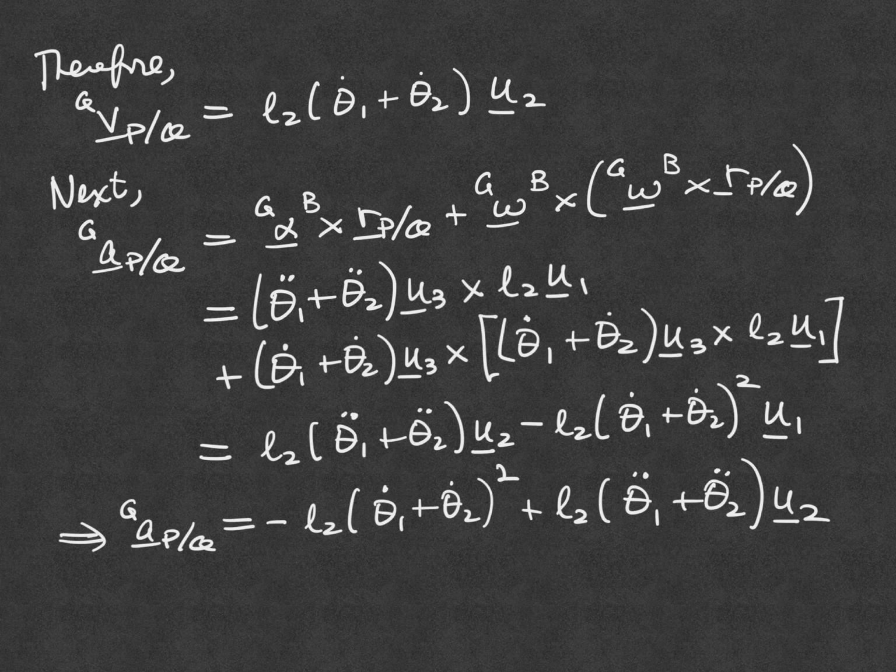So this problem was more complicated, but the kinematics still follow the same principles, which is that you have to add angular velocities, and then you have to express everything in the coordinates that are fixed in the last frame that's rotating, which in this case is the frame of the rigid body. So everything's always expressed when you're doing rigid body kinematics in terms of the reference frame that's fixed in the last body, which is the rigid body, and it's the body of interest. So the next concept, which adds on to the previous concept, is that of rolling and sliding.